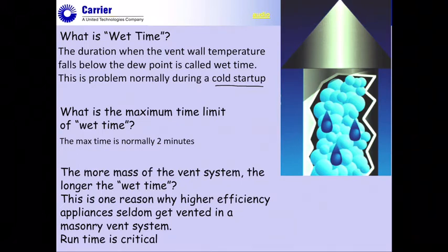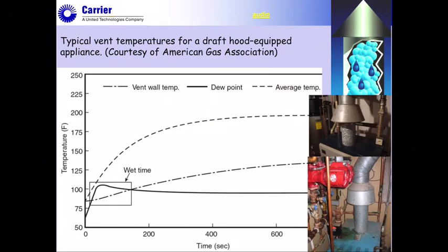Some of the boilers can get away with it, provided that the chimney is not too big, and provided that they get sufficient run time. But I put a note on your runtime being critical. The longer I can make those furnaces run, the less likely I'm going to have problems with condensation. So that's really very, very significant.